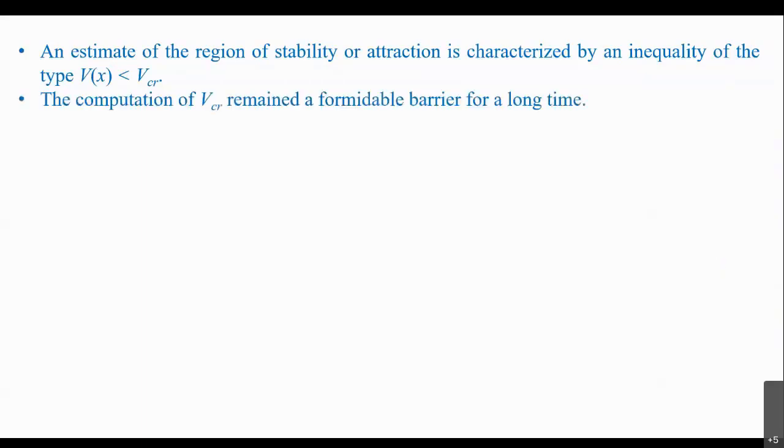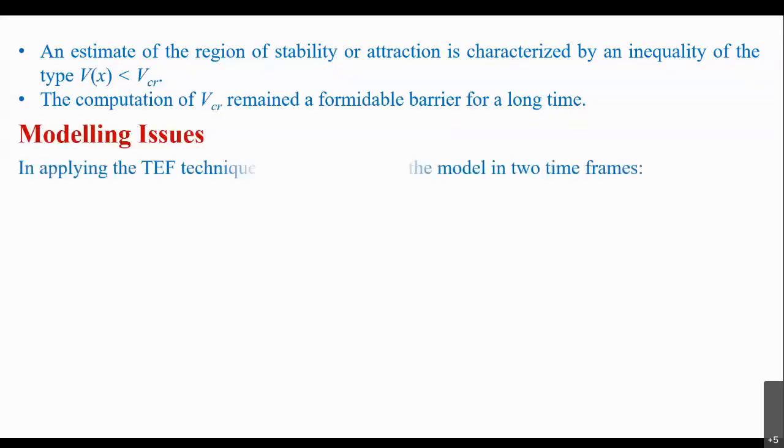So these things we have discussed, and we are talking about the modeling issues: how we will model the system to assess the transient stability using the Lyapunov method. That is, how to derive the energy function, how to find the critical energy, then how to find the critical clearing time, all those things.